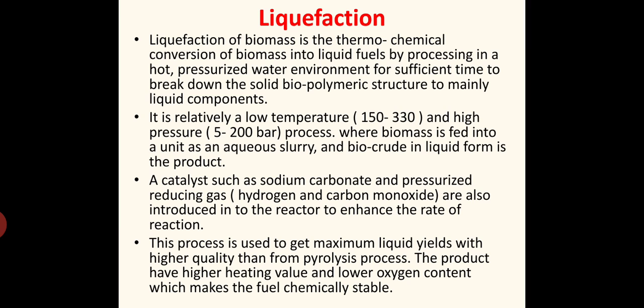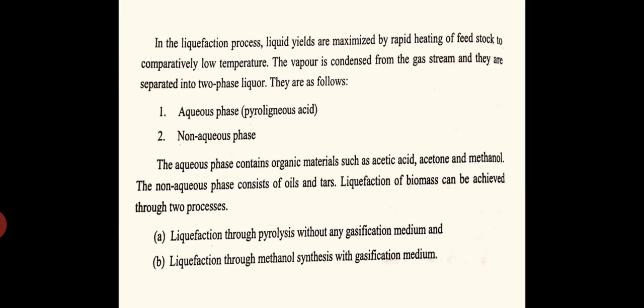So, the final product will have a higher heating value. Heating value means that by burning a unit mass of fuel we get more energy, it releases more heat. That is the meaning of heating value. So if the heating value is less, more fuel is required to produce the required heat. That is the advantage of going for liquefaction.